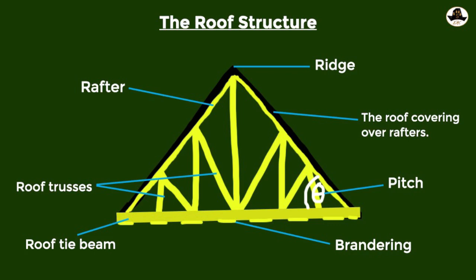So to show how these trusses will be stationed according to the specifications from the structural engineer, the structural engineer is to provide what we call the roof plan, which shows how he or she has calculated the forces of the trusses and what they have determined is the correct distances between the trusses, and how the pitch affects the positioning of the trusses.